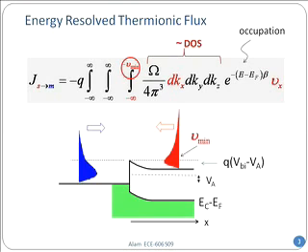Now, you also see that I have put in the limits. In particular, the other limits are infinity to minus infinity, whether electrons go in the plus direction or minus direction at whatever velocity, that's fine. They are not contributing to the current directly. But for the velocity along the x direction, I have a limit which is minus infinity, which is fine, because if you have a lot of energy, of course you can comfortably go over the junction. Nobody is stopping you. But by the way, this cannot be infinity really. Remember, all bands are finite. So we are talking about the bottom of the band to whatever is the top of the band. Now, for semiconductors, bands are about an eV or so. So that is about infinity.